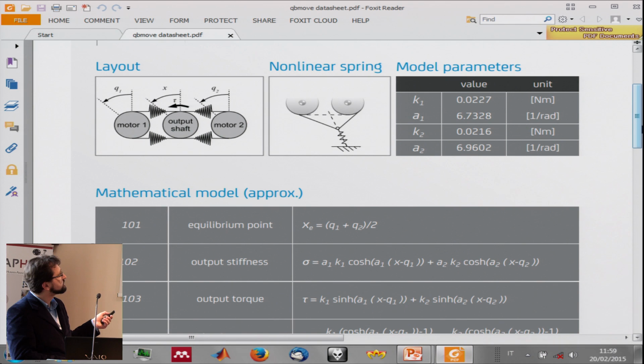So it's not much different from the VSA and VSA1 that we have seen before. If you remember, a tendon, in this case, not a belt, goes through a spring which is pulling, and if you pull both of the sides here, the tendon straightens, and so the ratio of transmission from the spring to the system changes, and the stiffness changes as a consequence.